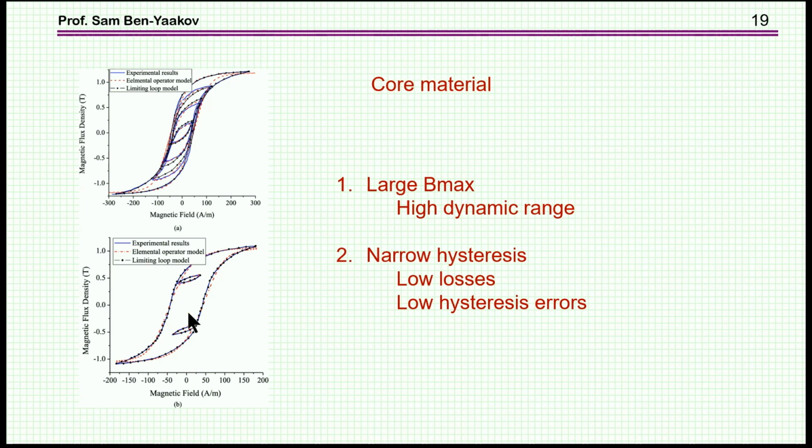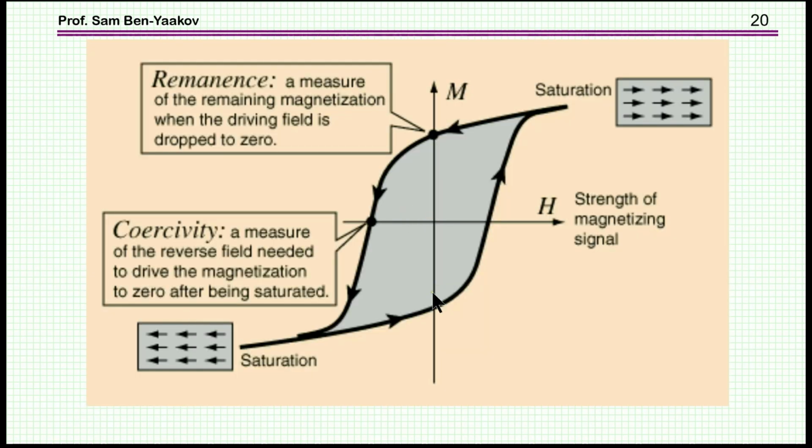Now, there's another issue here with the hysteresis, is that if there is a current which is bringing the ferromagnetic material to this region and then it goes back, and then you stop the current, this is the remanence value. This is like you've magnetized the element, and this is an error. You'll see a magnetic field, although there is no current passing.